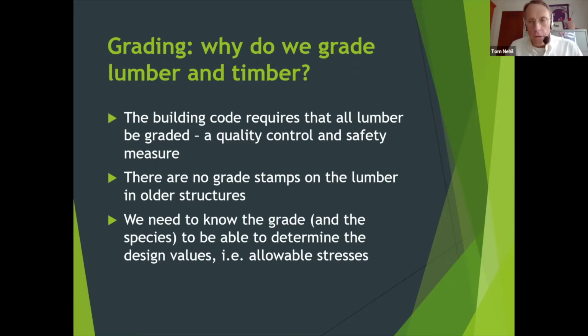And unfortunately, the old timbers in barns and warehouses and so on, there are no grade stamps. There's nothing to tell us what the species is or what quality the wood was. So we need to do it. We need to know that grade to be able to determine our design values, our allowable stresses, as you saw in the NDS supplement.